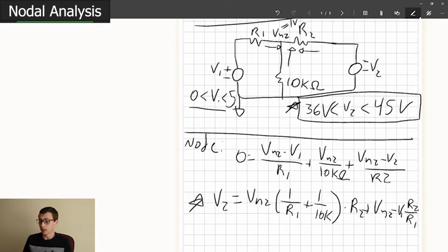Think of it like that. There is some power stage using this control signal to drive a power supply and make this output voltage. Normally you would just have a normal feedback network that would come back through R2 and be a normal resistor divider. But now we've got this extra control signal on that feedback network, so we've got a second source of current on that lower 10K resistor. In this case, it happens to be a much lower voltage, but that doesn't matter, because we can scale the relative effect of the output voltage and the control voltage based on what we need.